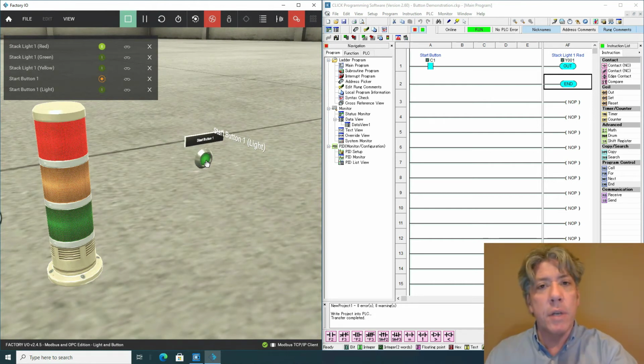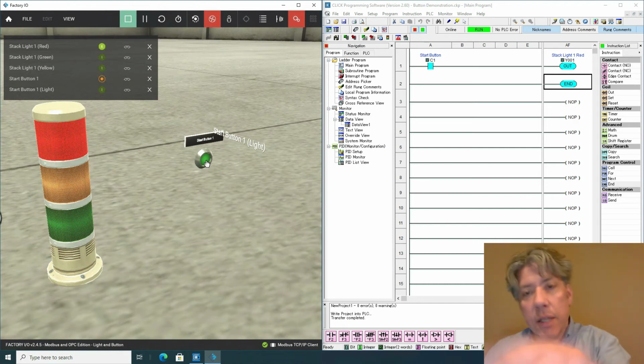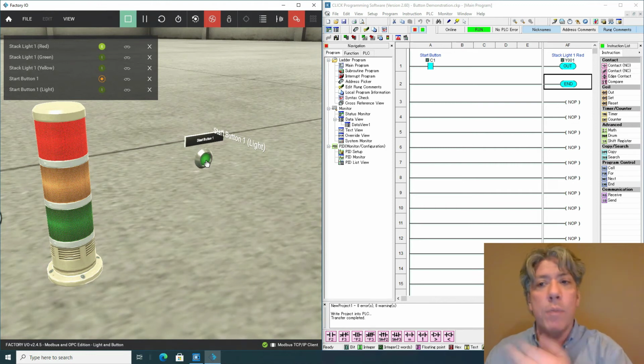that the monitoring shows that inside of the PLC, what the PLC saw was a memory address come on. C1 came on. And then the PLC said, okay, well, according to my ladder logic, now, by the way, I'm holding down this button so that the button stays active. In the ladder logic, when that memory address is on, that means I need to turn on output Y001. And so it did that.